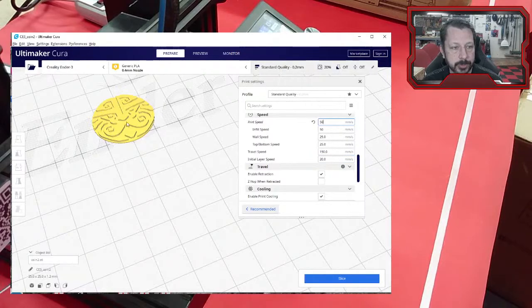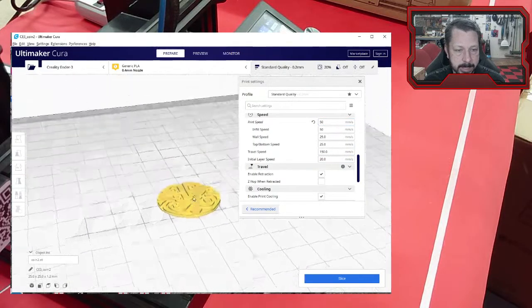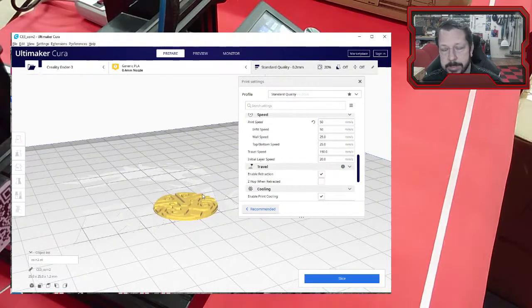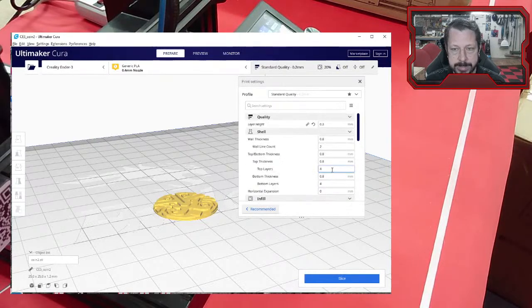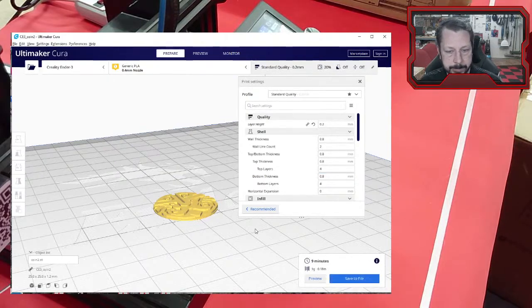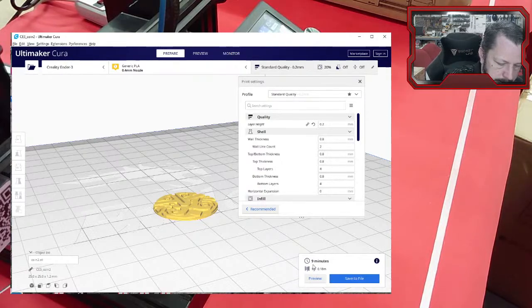That control how this solid geometry gets turned into code, G-code in particular, that can be read by the machine and interpreted into movements and extrusions and heating and all that kind of stuff. So I'm going to hit slice. It doesn't matter that you don't know what buttons I've clicked yet. By the end of the quarter, you'll know all those buttons. So it says it's going to take me 9 minutes. So I've got that file.